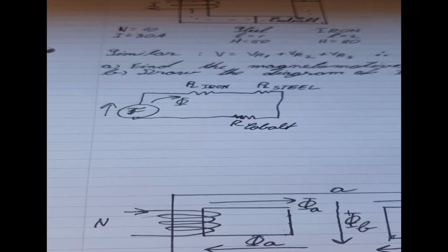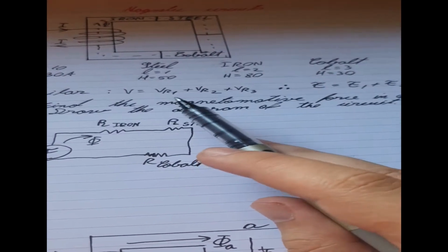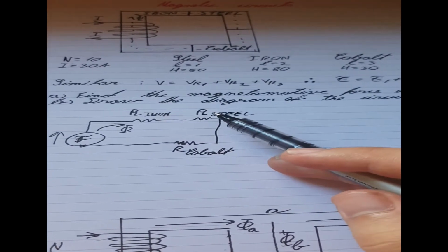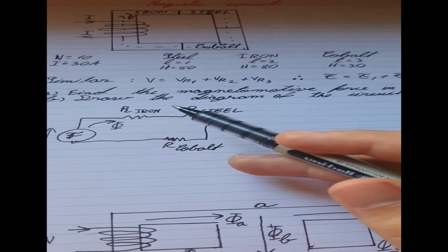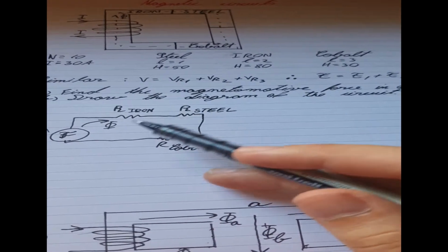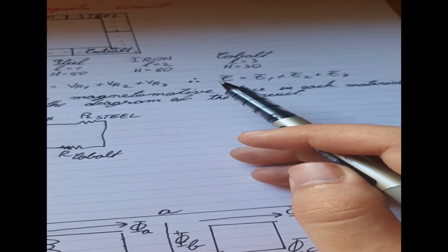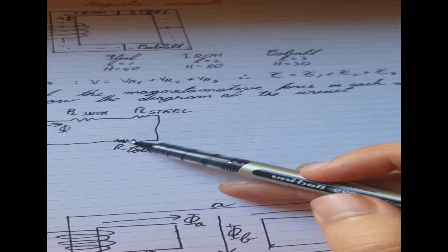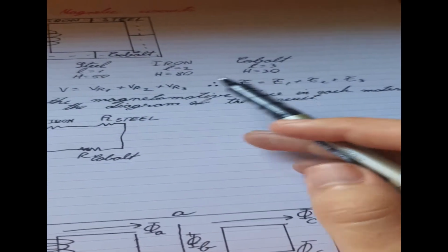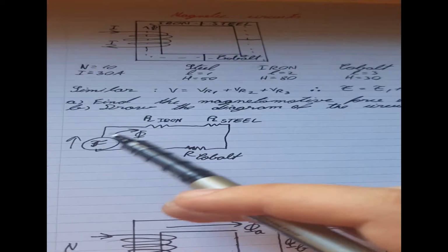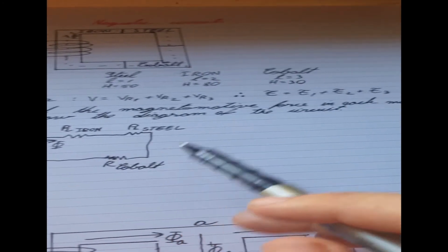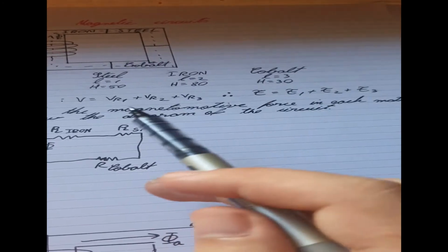That's how you translate a magnetic circuit into a simple analog circuit that you can see and understand. And they also have the same rules. For example, if you do VR1 plus VR2 plus VR3, it will give you the total voltage, because the voltage splits across the resistors. Well, it's the same for MMF. You can calculate the MMF inside each component, each metal type, and then get the total MMF from the source. It's just like normal circuits, really.